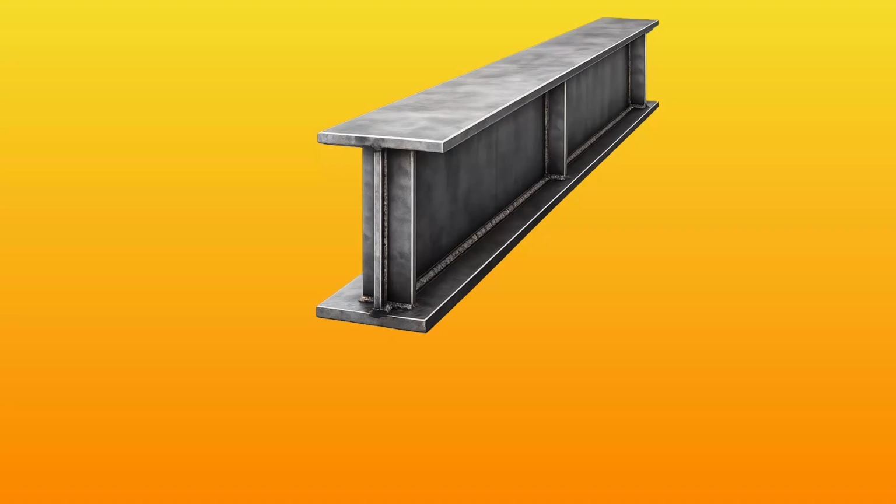The ones in the image here are shown as transverse web stiffeners. On major structures with really tall webs, you can also add some longitudinal web stiffeners. These can quite noticeably increase the shear capacity of the beam. So the key point here is that it's not purely about the strength of the material, it's also about the detailing.